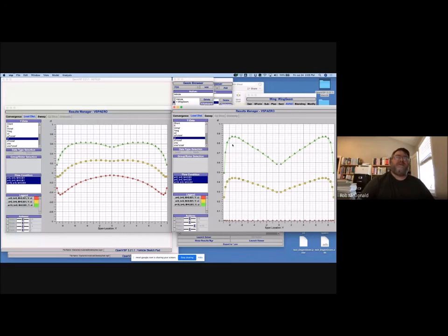And worse than that, stall doesn't happen at the exact same moment, right? Stall is going to happen, say, when you're on an approach and you're on base and you're turning base to final. So you're in the middle of a turn, you're turning into a headwind, there could be a gust, and you're at very low speed. So you're on the verge of stall, and you're turning base to final, so you're close to the ground, right? You're about to land. And what happens is that one wing is going to stall and not the other, right?